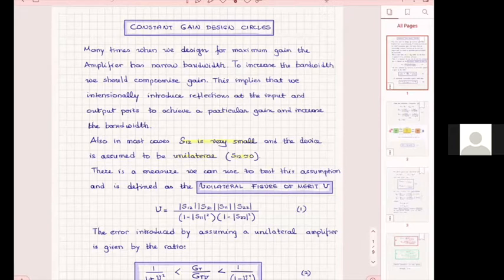The reason is very simple, logistically, or mentally, it's easy to understand, because the maximum gain is one value you get out of your amplifier, and that defines everything else. It defines your input network, it defines your output network. So it does not give you much flexibility, all right? It's one design at one frequency.